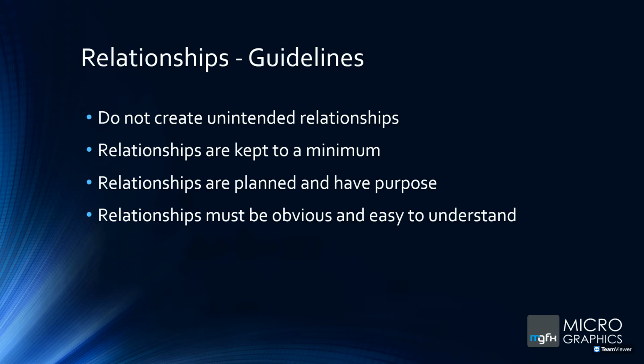Okay, so just guidelines. Do not create unintended relationships. Keep your relationships to a minimum. If you don't have to put a relationship in because you can control everything from maybe one source, then that actually does make a big difference. Plan your relationships, have purpose for your relationships.